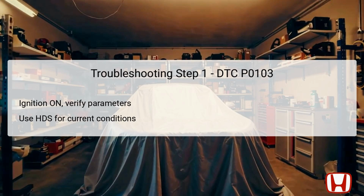If your readings show a value exceeding that threshold, the next step is to confirm that the failure has been replicated. In cases where the thresholds are not met but no failure is confirmed, it may indicate an intermittent issue, suggesting a need to check connections and terminals for possible damage or corrosion.